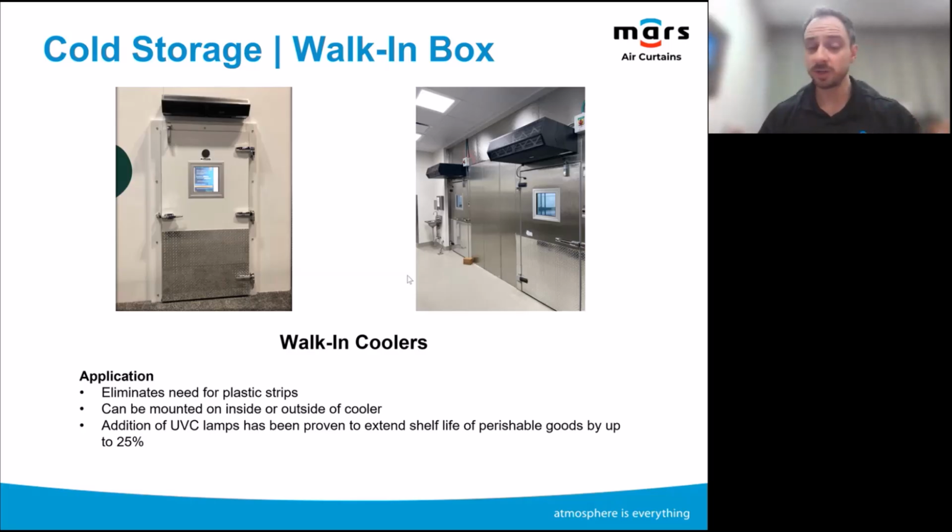So in cold storage, obviously you have cooler temperatures. Not only is that going to be more expensive if you're losing cold air as the doors open, with deliveries or something like that, but those cooler temperatures can create condensation as well. So if you have condensation, you can have slipping hazards. You can have issues, especially if you got strip curtains, with that condensation getting on the strip curtains, that can make them dirty, make them tough to get really in and out of.